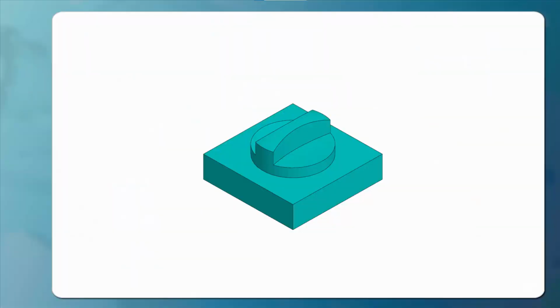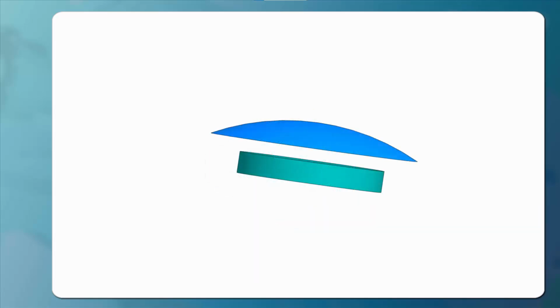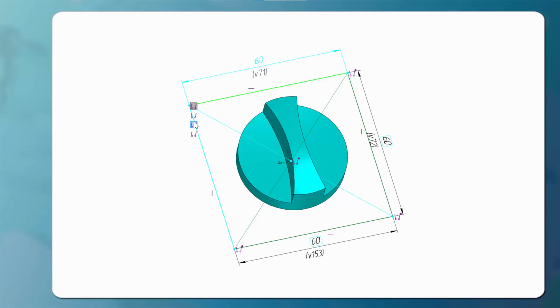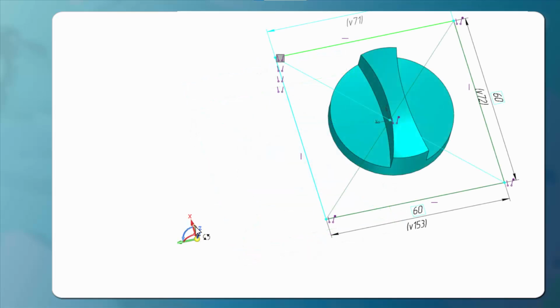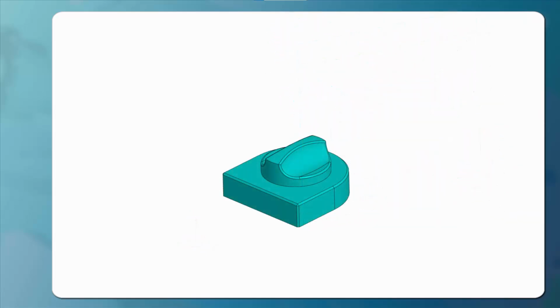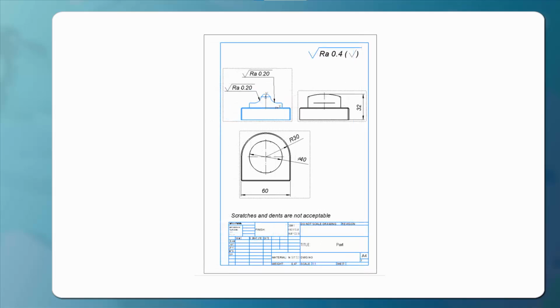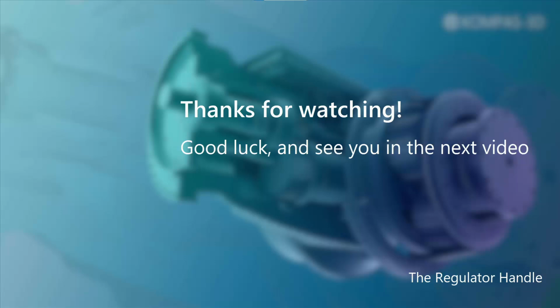In the course, we covered the different types of fillets and chamfers, created the extrusion limited by the surface, learned more about the constraints in KOMPAS-3D, and got familiar with the view orientation element. We added the annotations to the 3D model and generated the standard views. Finally, we transferred the annotations from the model into the drawing and adjusted the drawing. Join us in the next lessons to make your work with KOMPAS-3D more comfortable.